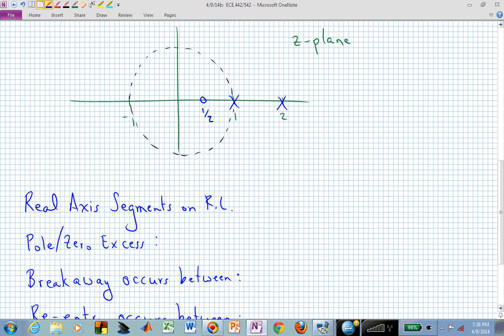the poles and zeros on our playing field, now what we want to do is start sketching the root locus. One of the first questions you should ask probably is what real axis line segments are on the root locus, and that should just be coming very quickly to you. We now look at each segment that exists and count how many poles and zeros are to the right of that segment. Doing that, we find then that we have these two segments of the real line that are belonging to our root locus.